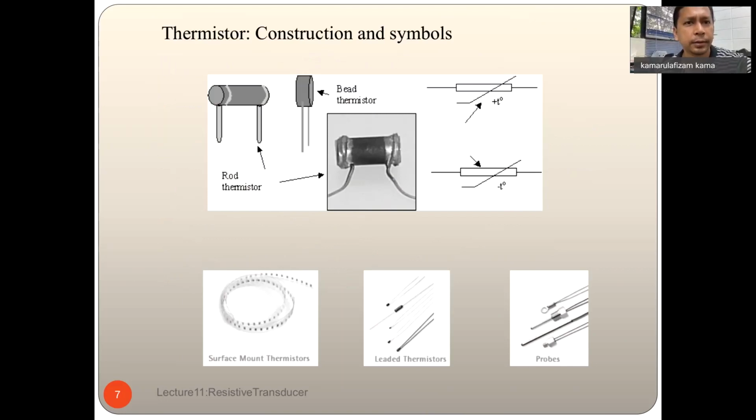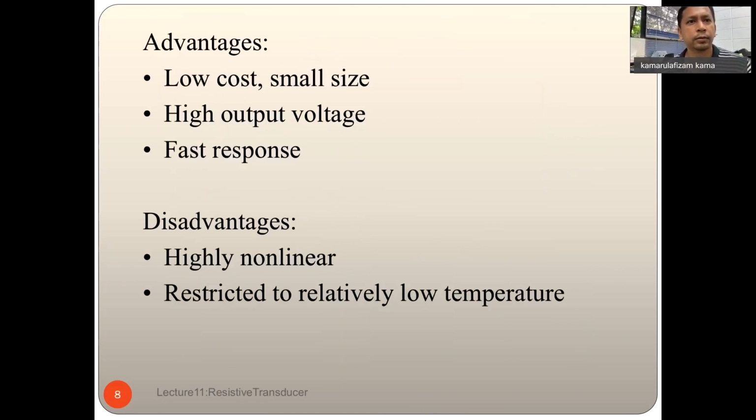This is another package of thermistor. So the advantages are basically low cost, small size, very high output voltage, and very fast response, because the package is small, so it absorbs changes in temperature quite fast.